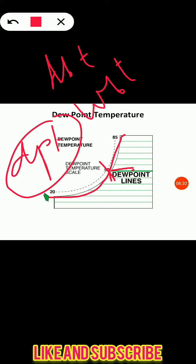And dew point temperature is the temperature at which condensation of the water vapor in the air starts. The line that we draw towards the right will cross our specific humidity line, which gives you the value of omega, in kg per kg of dry air or gram per kg of dry air.